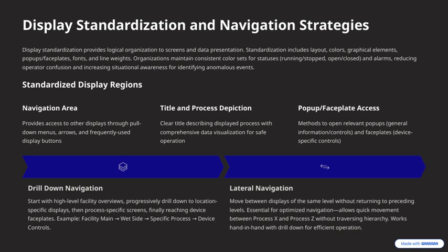All these strategies, lateral movement, drill down, clear titles, intuitive navigation, and standardization, work together to create a coherent and efficient operator interface, supporting safe and effective process management.